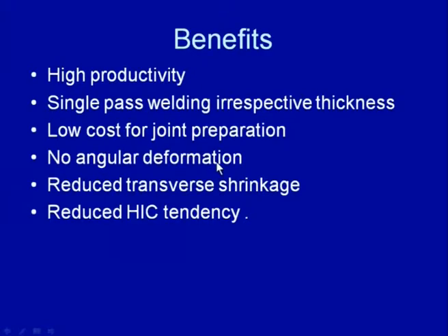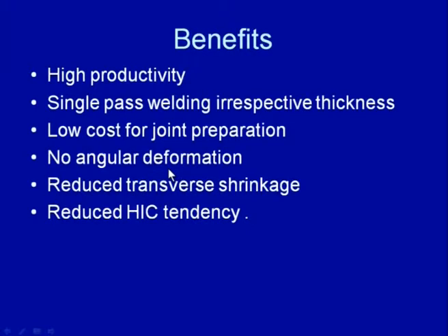No angular deformation, because the plates are kept in a simple vertical position, there is no edge preparation, and the weld metal is deposited through the thickness of the plates in one go, and the thickness of the weld metal along the length is also uniform. Because of this, no angular deformation takes place in electroslag welding.